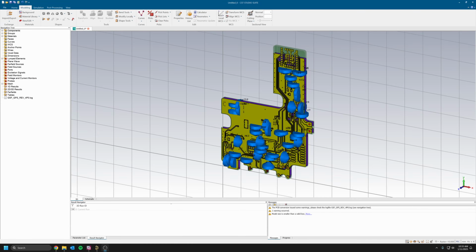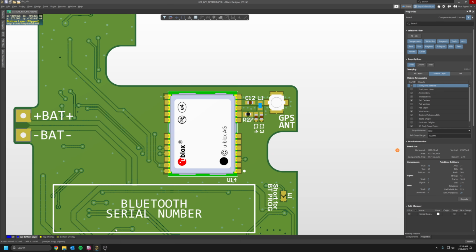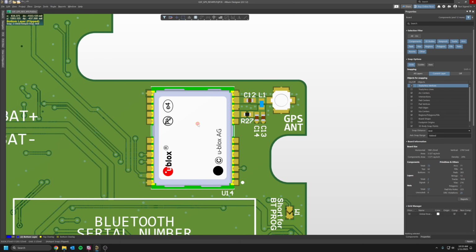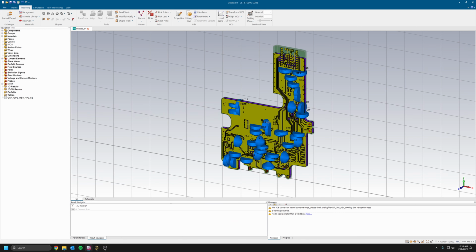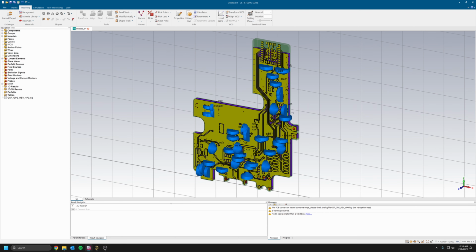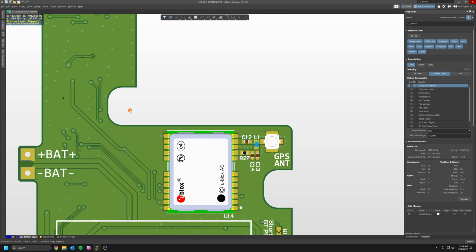Today I'm going to show you how to simulate a PCB. For instance, in this case, I want to simulate some traces for a GPS antenna here. I'm going to show you how to extract this with CST, a software that is used to do 3D EM simulations. The first thing we're going to do is remove most of the circuit because this is going to be too much for one simulation. So we're just going to restrain this area. We're going to remove most of the PCB so that the simulation is going to be much faster.